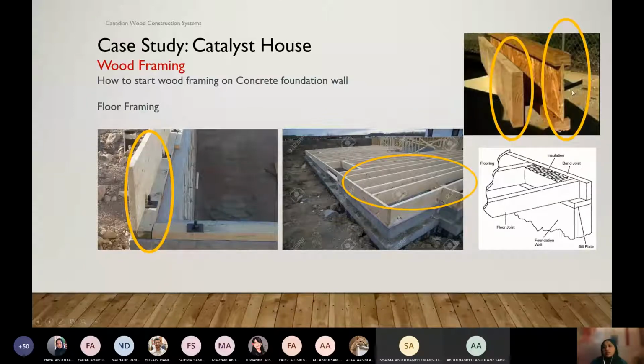The other option is engineered. That means these are totally made from wood chips and wood panels, and we glue them together, so we give them certain strength, or they're stronger. Those are made in a factory, so we call them engineered joists. Because this is very common practice nowadays, we use the I-joist because it looks like an I. So these are two options for joists. Either one is fine, and in terms of strength, it's fine. There are some advantages of the engineered I-joist, but otherwise both are the same.